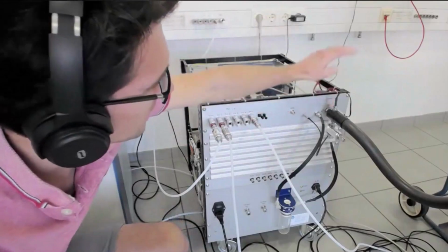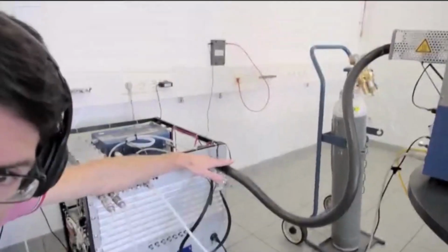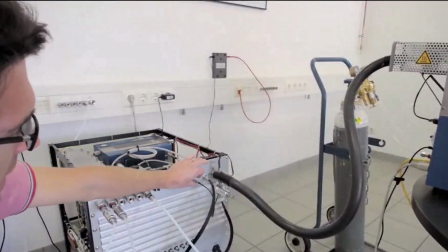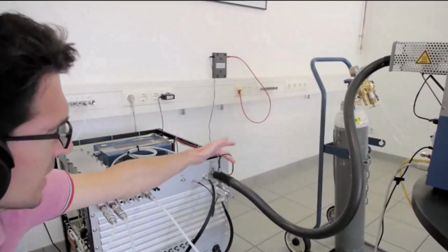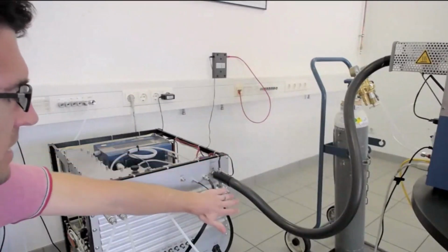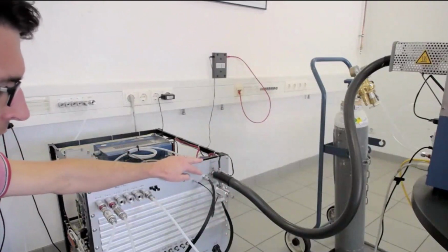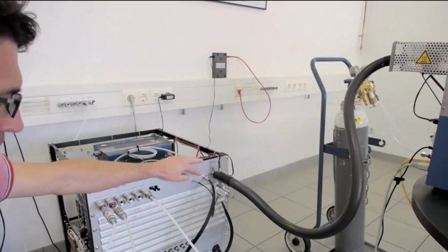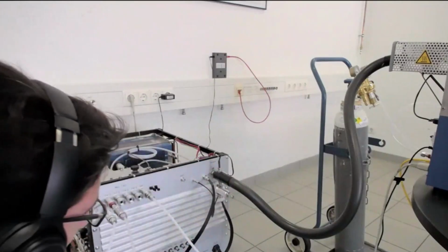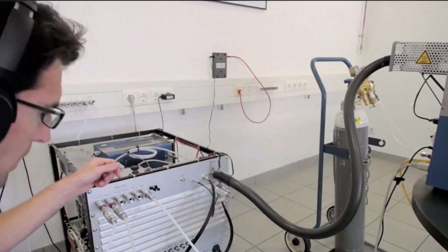Next we have the transfer capillary. This one goes from the instrument up to the gas oxidizer, which is connected here. We have a heating system for the transfer capillary; this is the plug on the far right. And we have a heating system for this needle valve, which we use in order to set up a certain sample flow. As you see, the gas which is pumped here goes through a moisture trap and then to the inside of the system, to the sample pump.